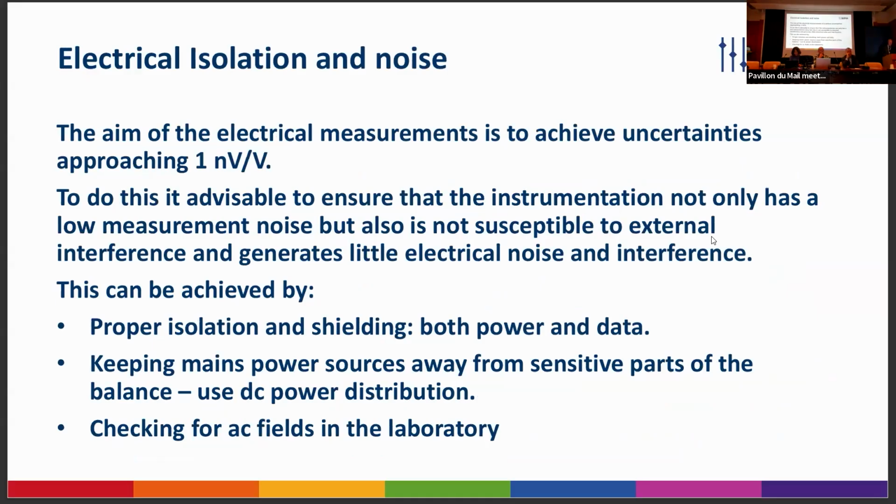The other thing that we need to think about in these measurements is that we want to try and achieve uncertainties of a nanovolt per volt. That is pretty difficult. And really, we need to ensure that the instrumentation is isolated. This is what Stefan talked about, the optical fiber data bus that I developed a long time ago. That was intended to handle the isolation of all the parts of the apparatus.